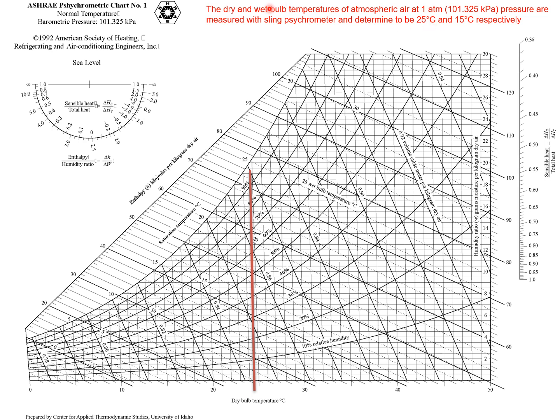Now we need to find the wet bulb temperature. The wet bulb temperature lines are shown here, the dotted lines. We have 30 degrees C here, we have 25 degrees C here, but we need to find where the 15 degrees C is. The 15 degrees C line for wet bulb temperature is shown here. It is inclined like the dotted lines here. Again, we draw another line there.